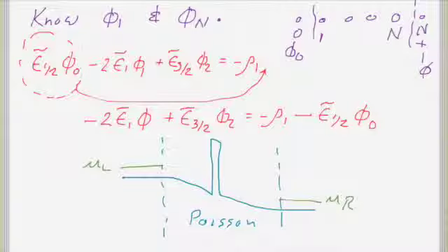And what we know is our doping density. Right? That's a given. You know your doping density. And since the electric fields are zero, you know that the doping density has got to equal the electron density, because these lead regions have got to be charge neutral.